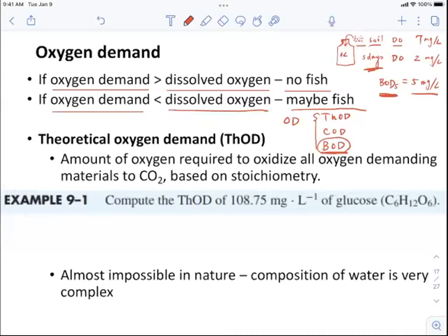But as we said, in wastewater the biochemical oxygen demand can be very high, like the butcher house, and it can be thousands. So what people do is dilute this wastewater first. You can dilute it several times, even 100 times, and then measure that. If the BOD5 turns out to be 5, and you multiply it by the dilution factor, for example 100, you can get the biochemical oxygen demand in the sampled water, 500 milligram per liter. So this is the idea of how to measure the BOD.